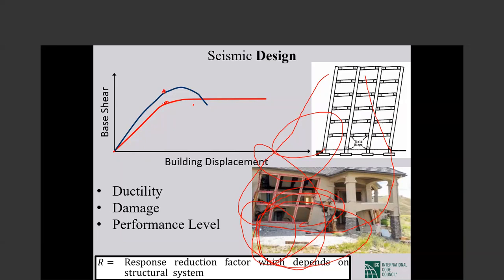And a design level earthquake is just a 475-year return period earthquake. It's not 100,000, 2,000, 3,000. It's just 475, so it's not a big deal. But again, even for that, we divide the base shear by R: 1/5, 1/7, 1/9, 1/10. So we reduce really drastically the amount of base shear. So we know that strength is very much less than the applied load, and this gets damages.